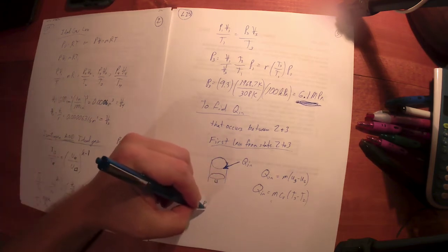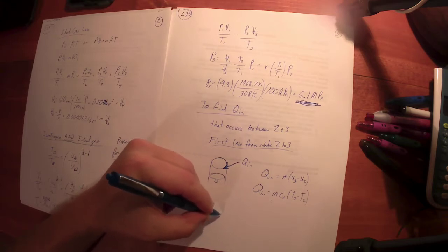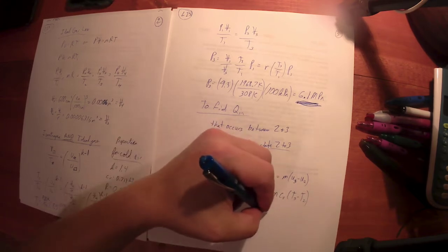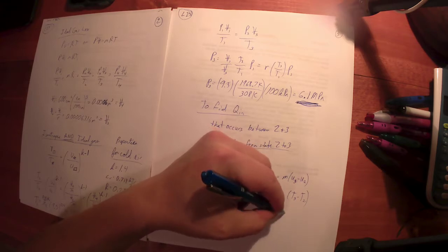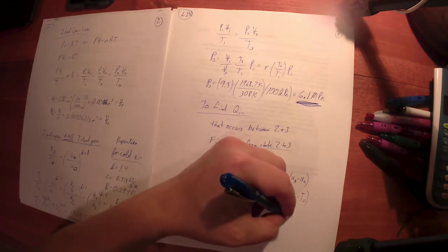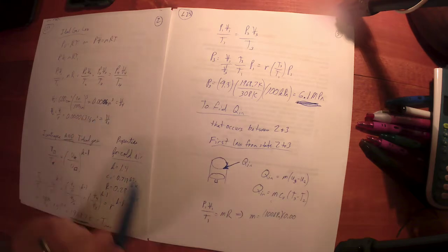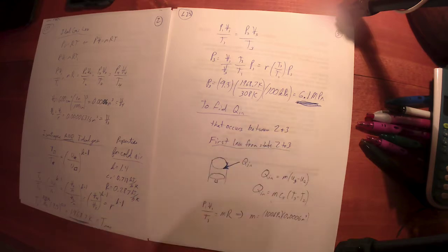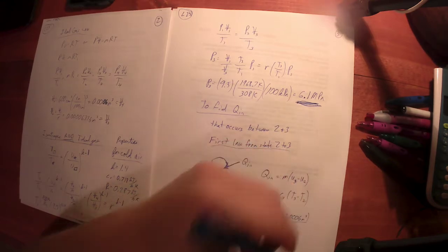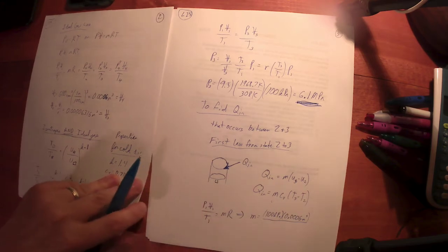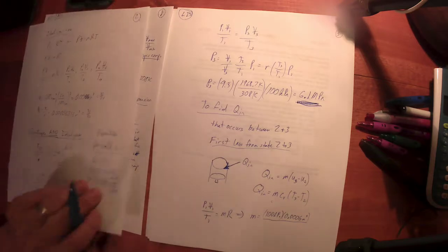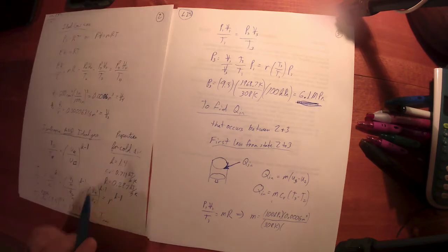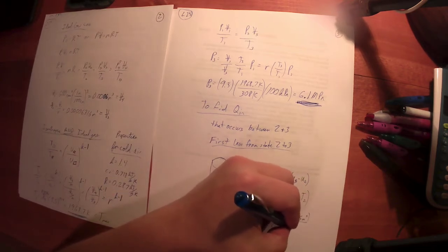So to find the mass, P1 V1 over T1 is equal to mR, meaning m is equal to P1, that's 100 kilopascals, over V1, that is 0.0006 cubic meters, you said that's 3 zeros and a 6. That's V1, divided by T1, we've already said earlier that was 308 Kelvin, right? It was 35 C, which is 308 Kelvin, and divided by the R value, which we looked up earlier, 0.287.